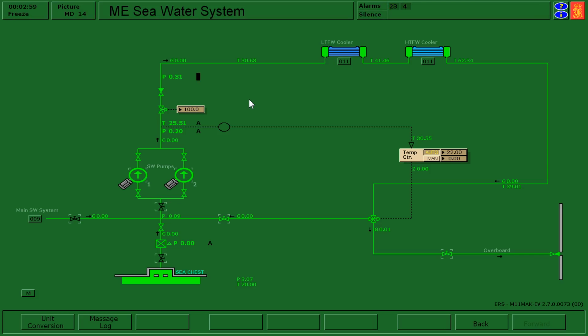First thing that I want to do is acknowledge that I have an alarm going on, and I'm going to silence the audible alarm. So the beeping that's going on, what I want to do is stop it. F12 is the key in the simulation lab to silence the alarm. I'll do that now. So silencing as my first course of action has a couple of reasons. First of all, by silencing the alarm, it allows me to get rid of the noise and allows me to concentrate on the task at hand, which is to try to solve my problem.